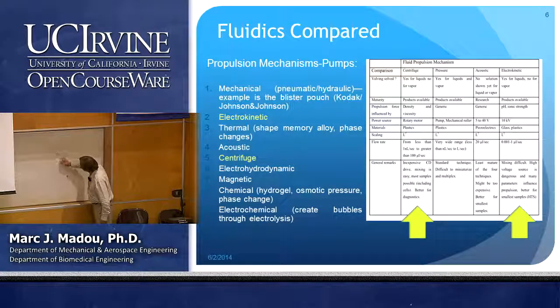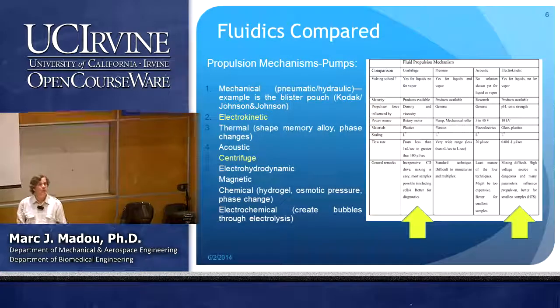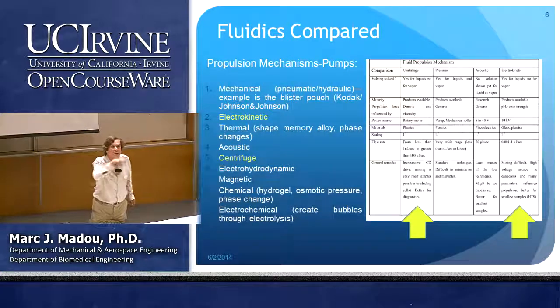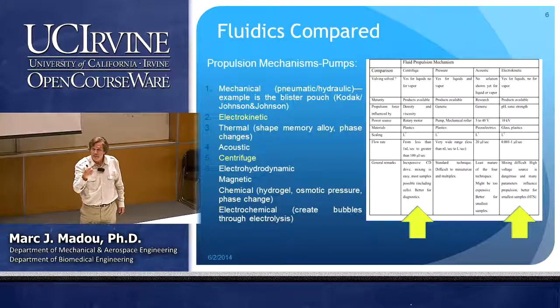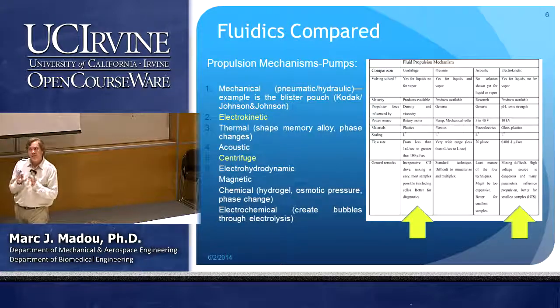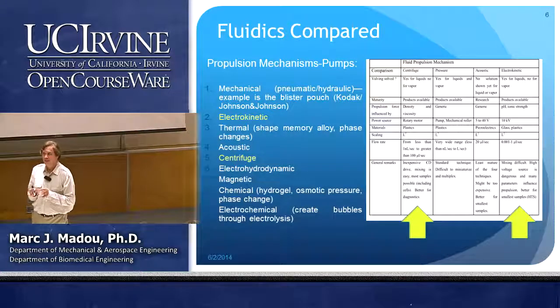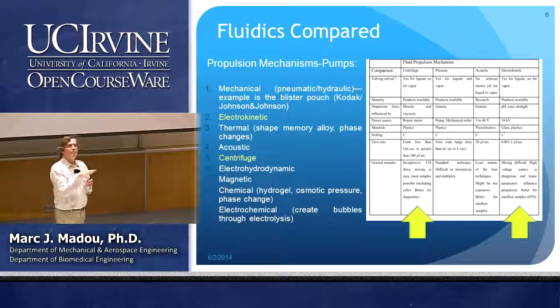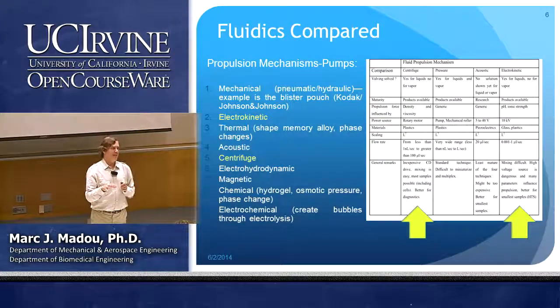Because, look, before the vapor spreads out here, the liquid is stuck here because of capillary tension. And I need to put quite some centripetal force to unlock this liquid to make it go to this chamber. I will come back to that later. I will actually show an equation that shows at what rotation speed the liquid will actually start moving. We call that a passive valve, but it's only a valve for liquids, not for vapor. And you cannot believe what big problem that is actually for all microfluidics.